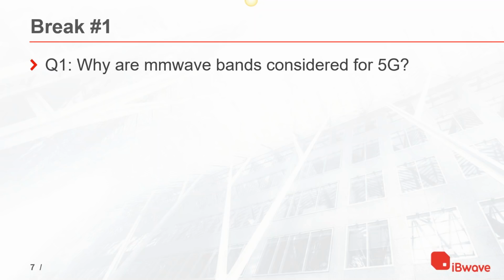For your 64 QAM, for example, it can go up to 6 bits per second per hertz. Obviously, it's going to be a little bit less than that, but when you multiply 6 by 850, you see how high a data rate you can get even with a 64 QAM, not 256. It will go even higher. So that's the reason why we are seeing it now.